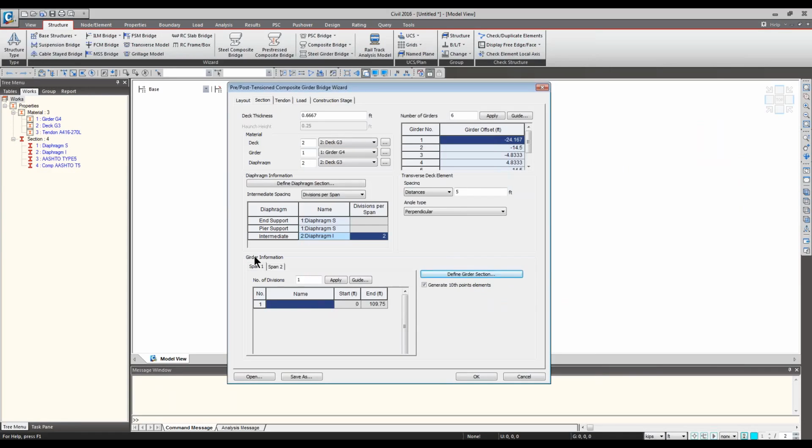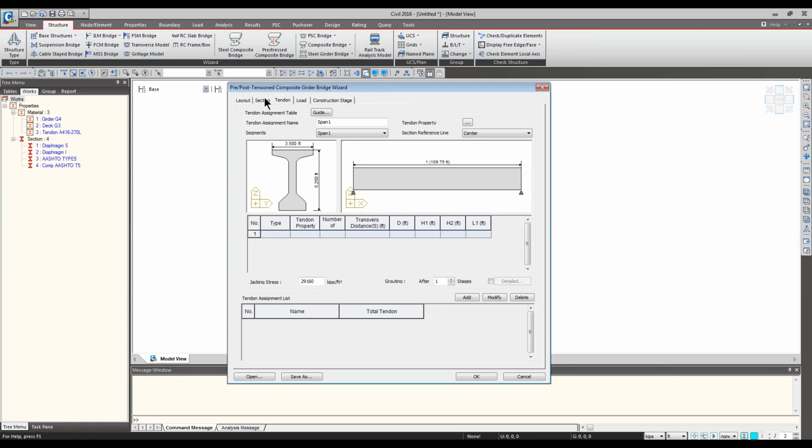So coming back to the girder information, you now have the section appearing on your drop-down list. So pick it, span 2, yes, there we go. And this option seems really minor because it's almost not noticeable, but it's very, very important and useful. For an FEA program, it's difficult to extract the output at the 10th point. You have to manually configure the node and element ID, but with that option, you could have the program do that automatically for you.